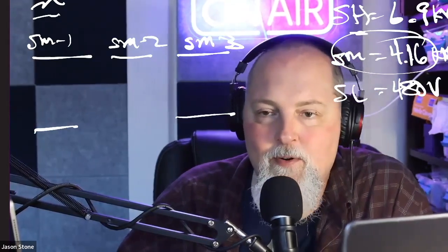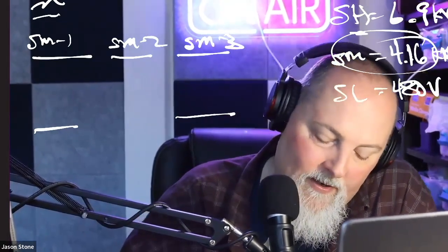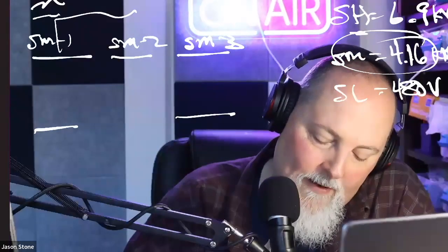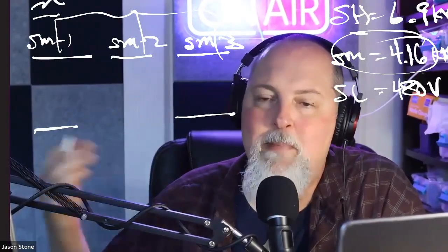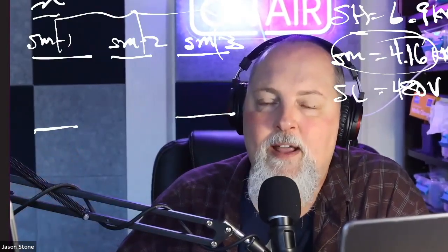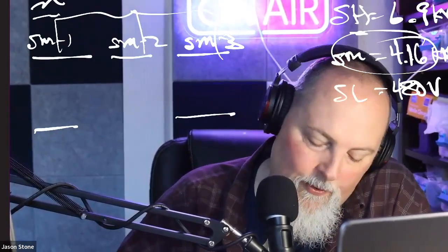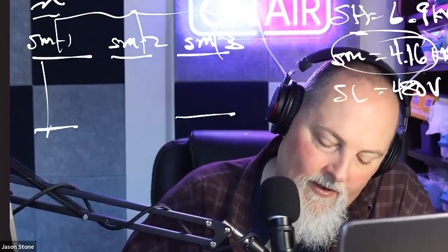Now, before we get to that, these 3 buses are powered by this transformer. So this transformer gives them all power. And they have 2 loads on each one. One of them is a circ water pump, which is a massive 2-story tall pump. And the other one's a condensate pump, again a big pump. But they also provide power to these 2 down here, which are our safety related buses.